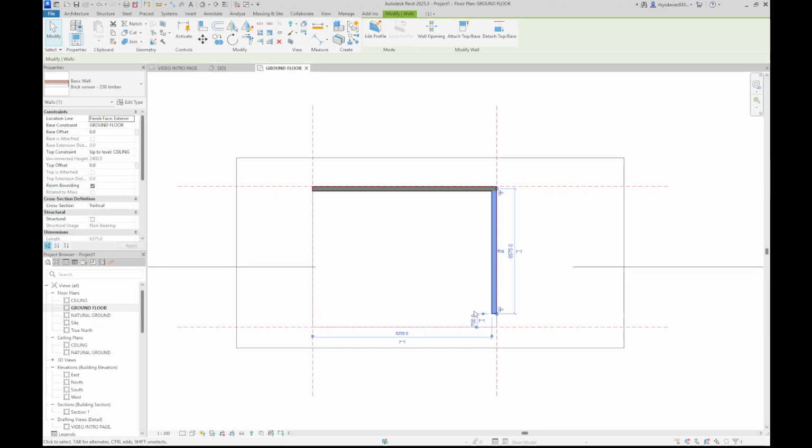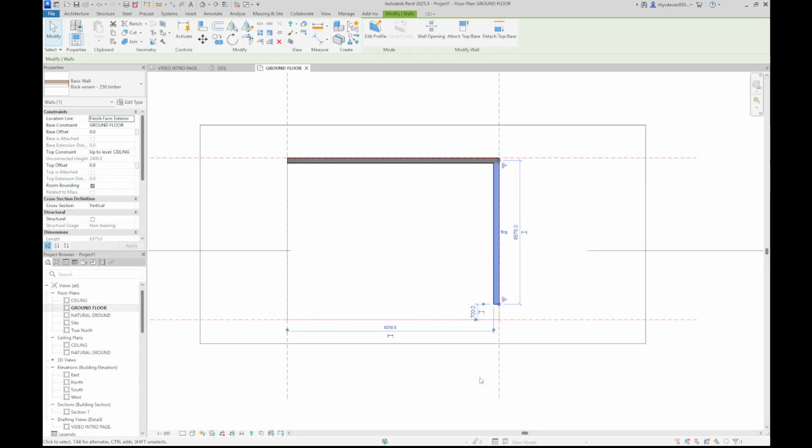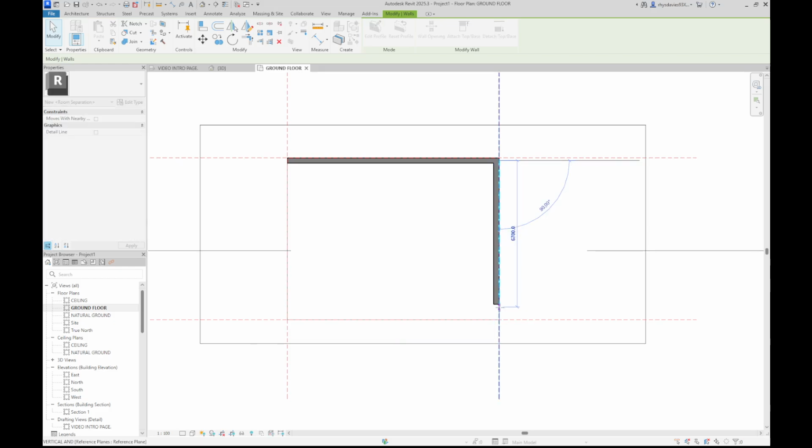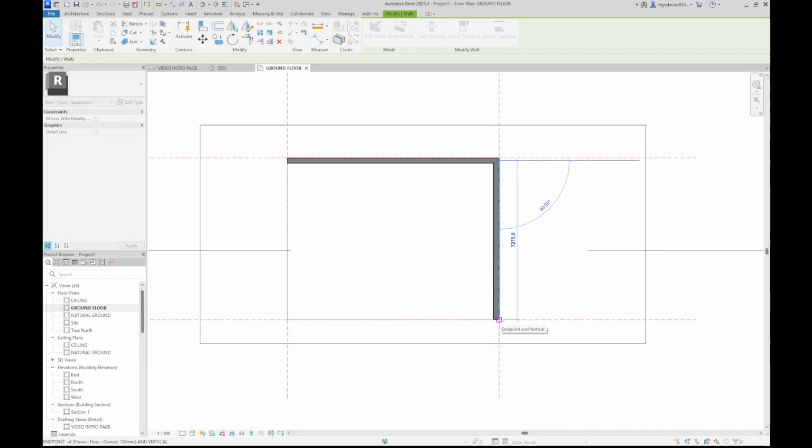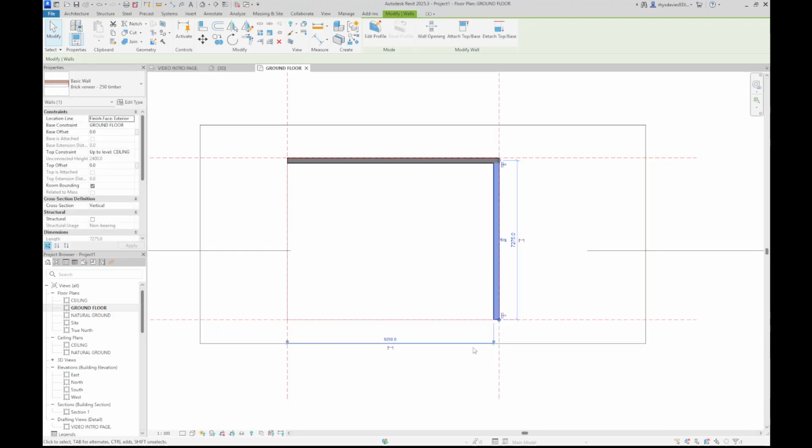I clicked that button a little bit earlier and that was purely unintentional. Okay, but this gives me the opportunity to introduce these little grip buttons here. Okay, so these little blue dots. So if I want to, rather than drawing in another wall, all I need to do is hover over that little blue dot, grab with my left mouse button, keep it holding down, and then I can drag to reposition that wall. That is the best way of doing that.